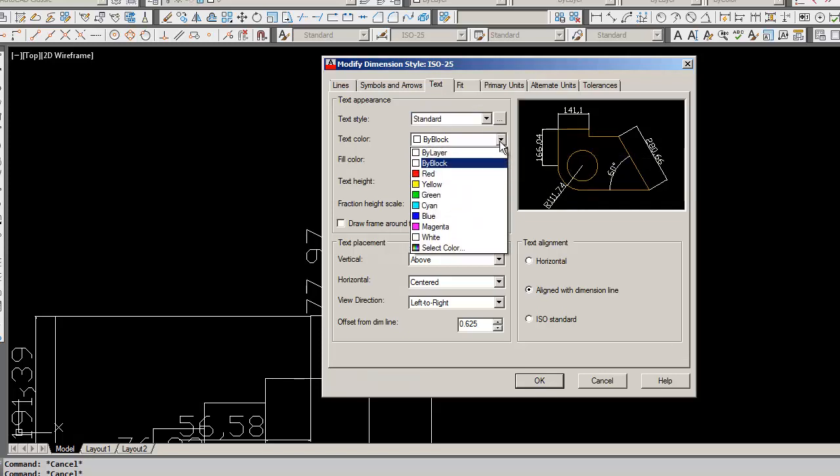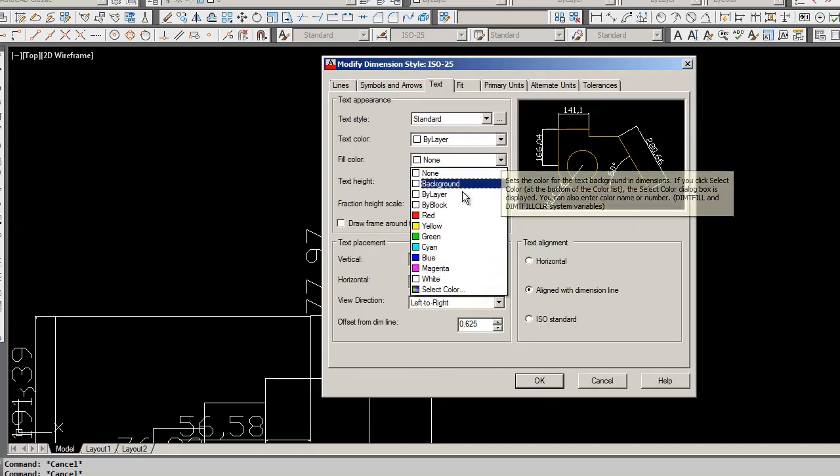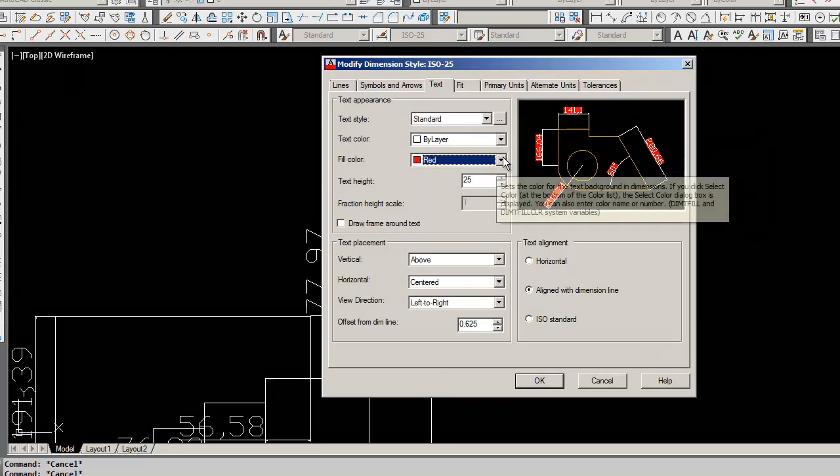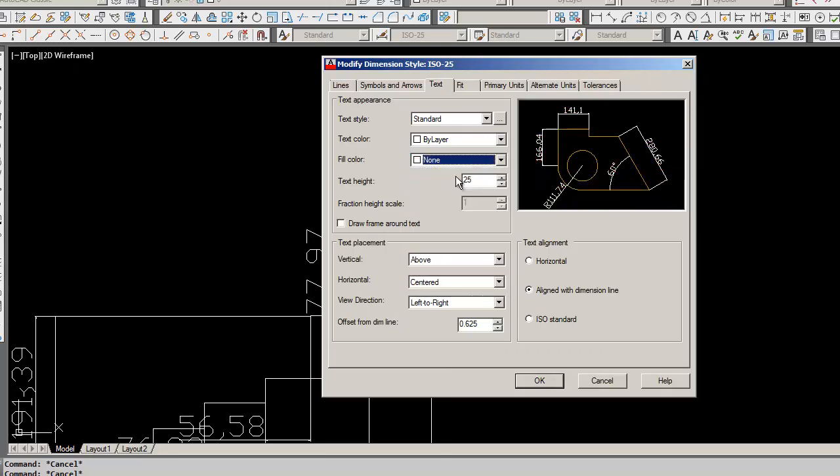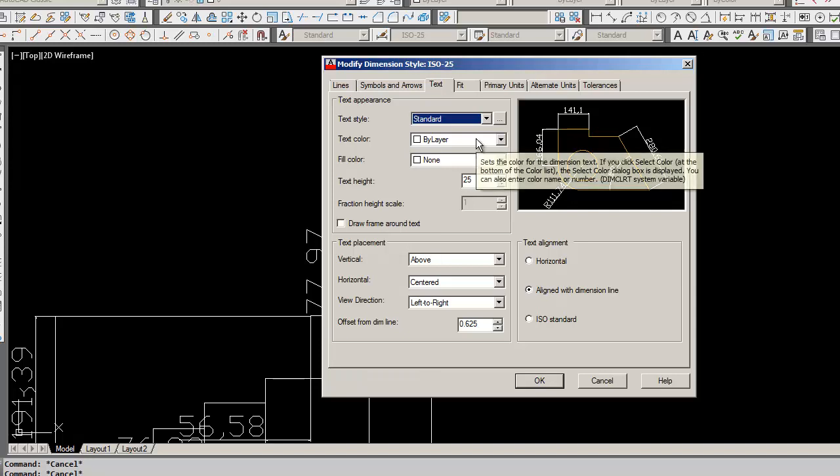And block, we will select the layer. Whatever layer you have for dimension, the same layer, the text matter will be there. I will come to that. And then the color. You can select a color for the dimension. You need not have any color for the dimension. It will be like this. And then standard. Here there is one standard. And here you see annotative. That I will discuss later on. Now at present, we will learn about this. Annotative is a new feature adopted after the 2007 revision. So we'll discuss the styles, standard style.